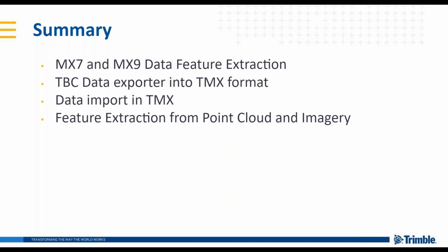What is the minimum density of the point cloud which is good to extract the features automatically? Well, I don't know how to give you a number on that, it's a bit difficult. We usually use our scanners at the full maximum range and full maximum capacity, meaning we're recording 1 million points from each scanner, 250 rotations per second.